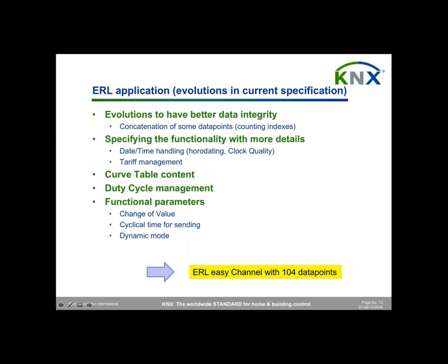If the clock is coming from the meter itself, it's high quality because it's directly linked to data. If you get clock from KNX devices that is not synchronized with any internet clock or any other good clock, you may have a clock quality that is not the highest, and it must be set in the timestamp that the date-time is not with the highest quality.